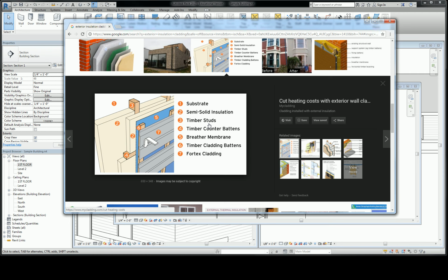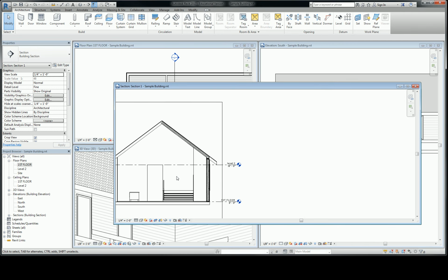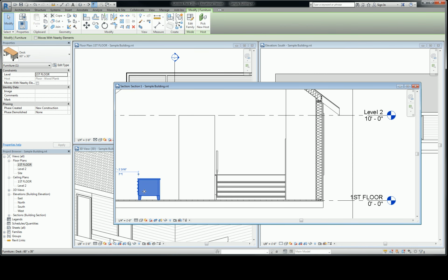So another interesting element, when we get to families, guys, you're going to understand how these things behave. But those system families, like a wall, for instance, it's called a wall, right? And these other families that we create, like the desk and the doors and stuff that I have in here, those are families that have an orientation, right?